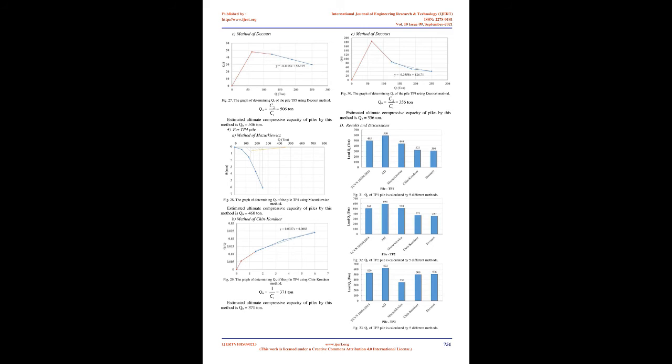The ultimate load capacity of 4 piles are shown on the figures from Figure 5 to Figure 7 when calculated by 5 different methods. Let the symbol Qmax be the maximum load of the static compression test at the site and Q is the estimate of the ultimate load capacity of the pile by different methods. Calculate the ratio between Q and Qmax and those values are compared between test piles as well as between different calculation methods. The results are presented in Figure 35 and Figure 36.